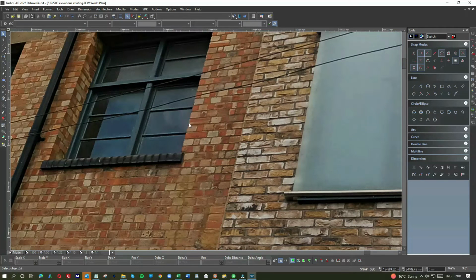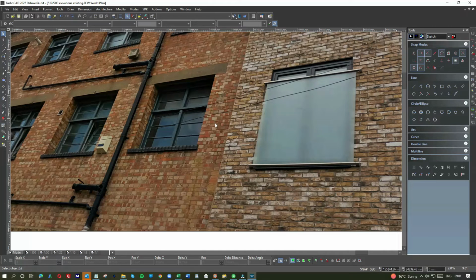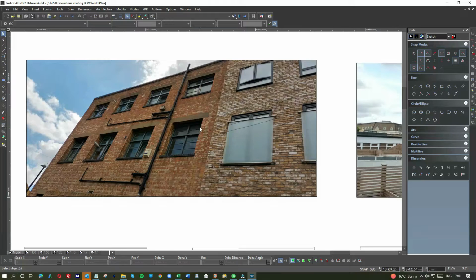If you take one brick, 225 wide, including that little bit of mortar, and again 75 is one brick and one piece of mortar. Brick is actually 65, and we allow 10 mil for the mortar. So all we need to do is to actually count up the bricks to get our heights and widths.